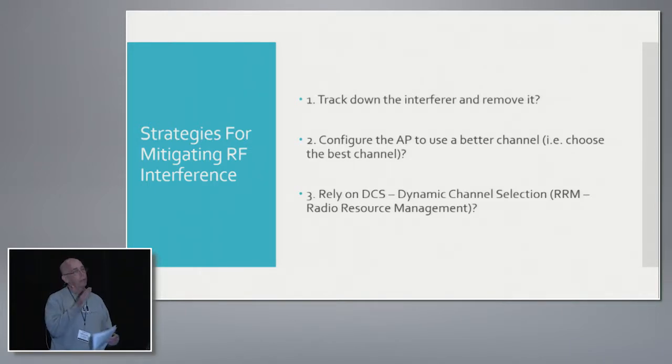Even when you're pointing right at the source, and even when you move a little bit away, the delta in the spectrum analyzer is really small. So it's not like when you're pointing right at it, you see a big peak of interference, and when you point away, it goes way down. The delta is really small. So even if you wanted to track it down, if it wasn't an obvious interferer, it's hard to do for that reason. And number 3 doesn't work so well.